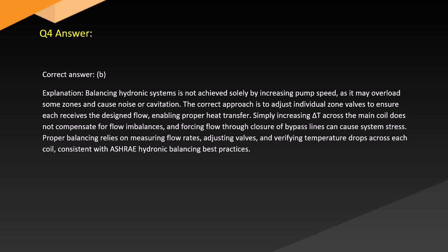Answer. Correct answer: B. Explanation. Balancing hydronic systems is not achieved solely by increasing pump speed, as it may overload some zones and cause noise or cavitation. The correct approach is to adjust individual zone valves to ensure each receives the designed flow, enabling proper heat transfer.